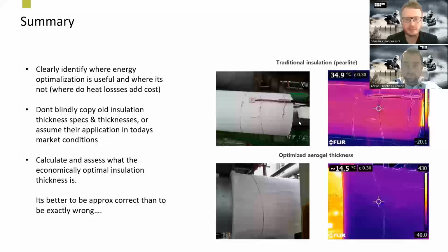So yeah, let me just recall the first question we received from one of the participants. Are insulation thickness tables adapted to the insulation material commercial thickness available, in terms of the temperature range columns in the table? Yes, very often the thickness tables are divided into the thicknesses actually available from the manufacturers. So if the material is available in, for example, 1-inch steps or 10mm steps, this will normally be shown and reflected in the insulation table as well.